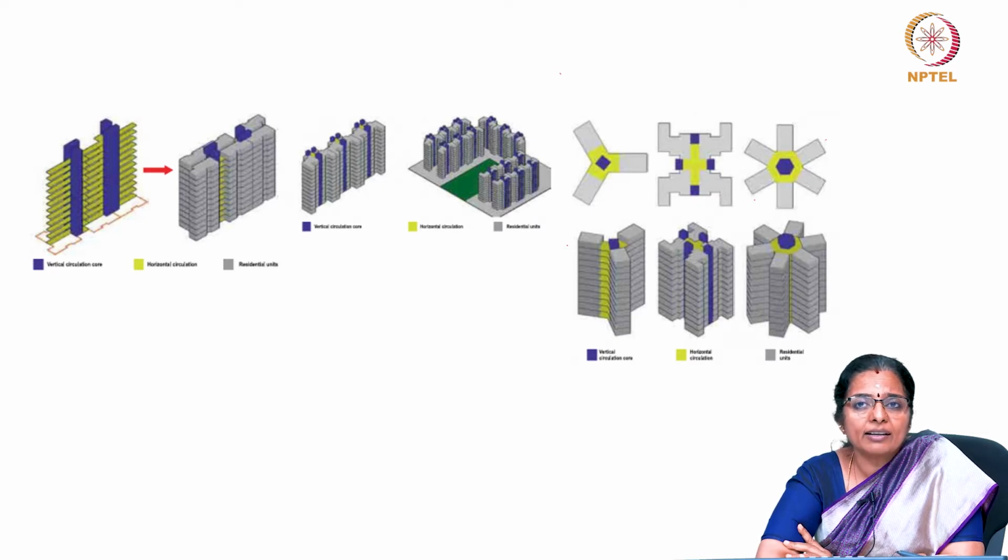In the hot and dry climate, the envelope should be designed so that it remains shaded for the greater part of the day. The external walls should be so planned that they shade each other. In the last class, we had seen how they can be made to shade each other, and this slide is also a reminiscence of where we left.